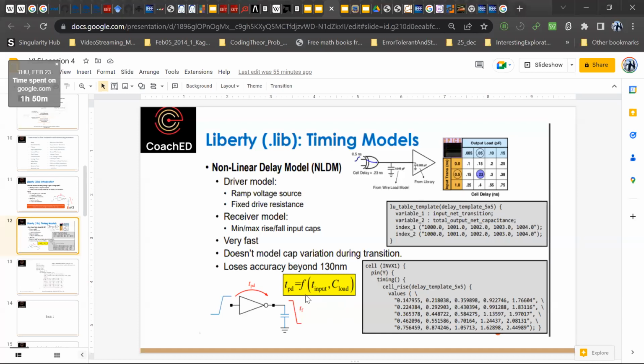You may have heard of STA. There will be some timing analysis tools which get used. The timing analysis tool is then responsible for taking the output transition value which you get from the pre-characterized model, and then it uses some equation to get the wire RC effects, and then sees the effect of a delay over the wire. So the pre-characterization never accounts for any wire resistance. Okay. Okay, so thank you. That's a good question. Any other questions?